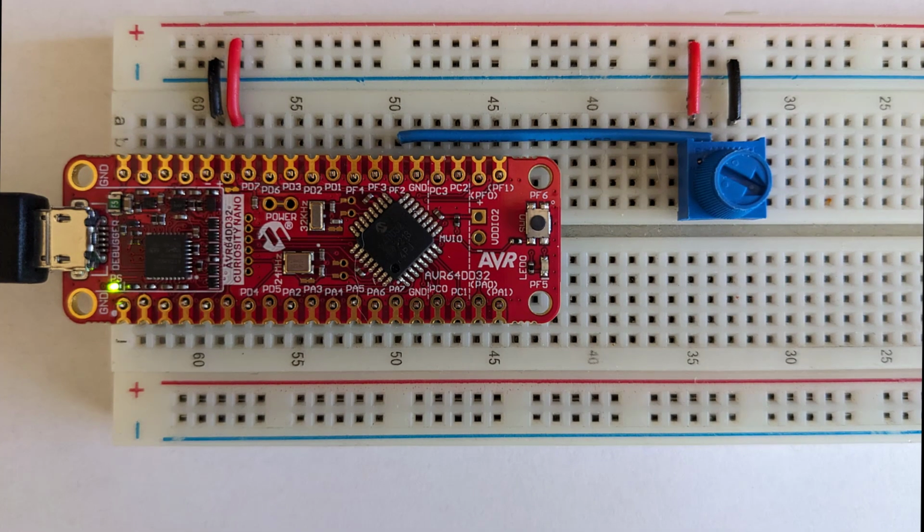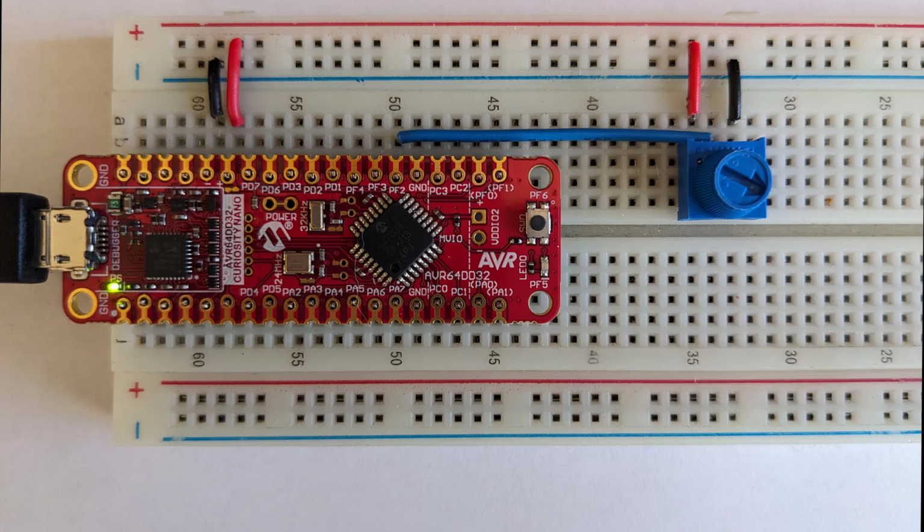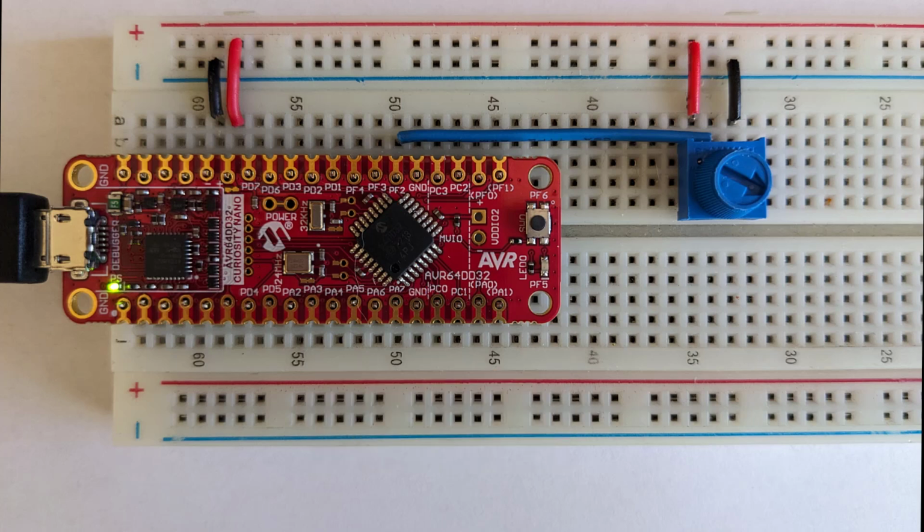Before we write our ADC driver, I will set up the hardware. I have a 10K ohm potentiometer and have connected one side to VDD, the other side to ground, and the wiper is connected to pin PF2. So now let's start on our ADC library.